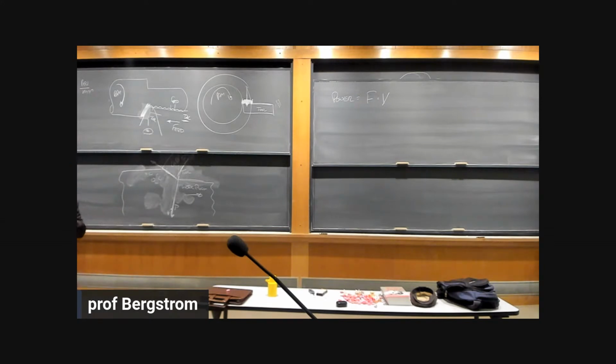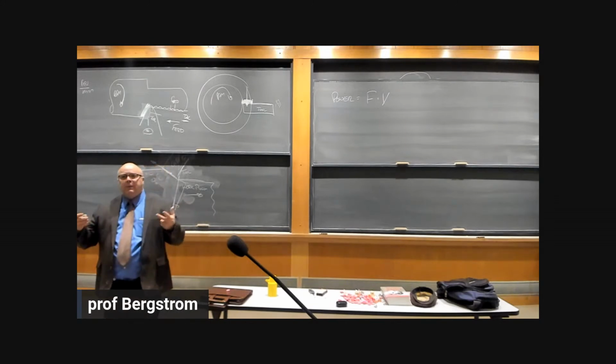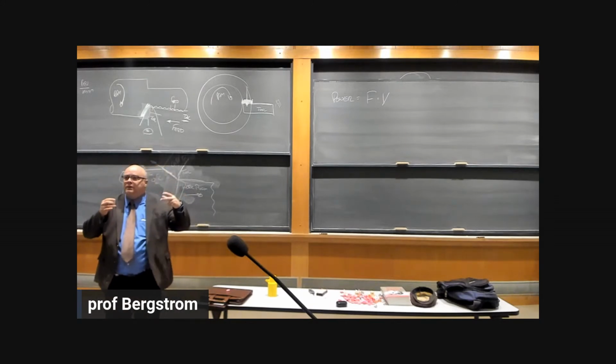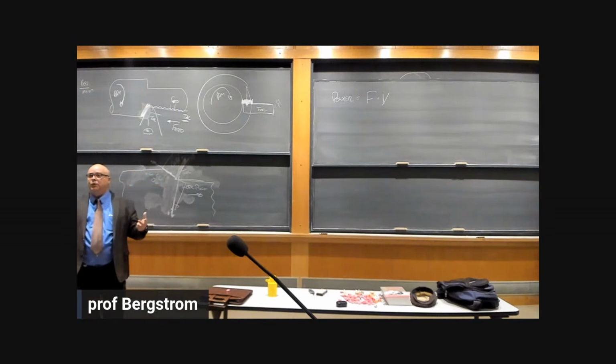And since we want everything to add together, the force that lines up with the shear force has got to be normal to that also. And so we've got 3 orthogonal force systems. Depending on if we're interested in the bulk material properties, or the tool-chip interaction that's happening right here that slides along, we can convert between those force systems.